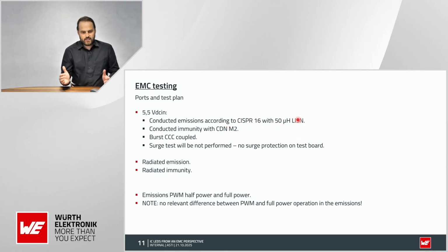Again, as I mentioned in the first webinar today, I like to measure the DC input as an AC input. My idea behind this is that when I pass the AC limit with the DC input, I will also pass it with an AC to DC converter, which maybe is not reducing the noise that we are producing with our board here.